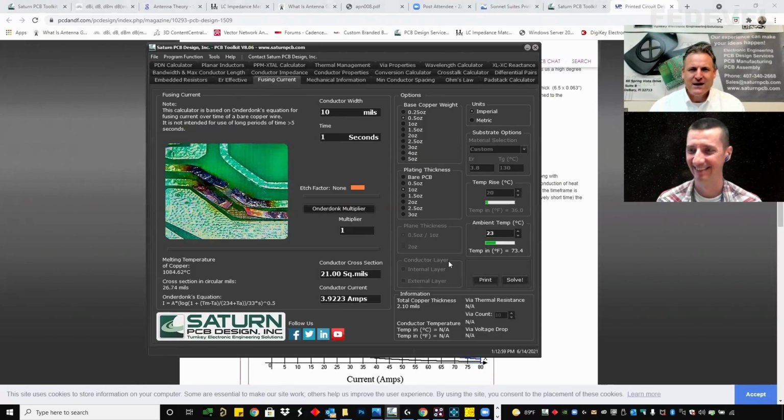I think a lot of it has to do with the trace in the picture. What happens is the glass transition temperature is exceeded, and the material just underneath the trace melts or burns away or becomes loose. And as soon as that trace pulls away from the thermal heat sinking of the board itself, then it burns up immediately. But if you can keep the trace on the board, they can handle a surprising amount of current.